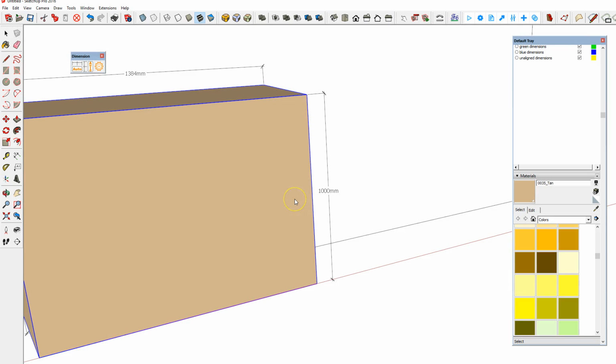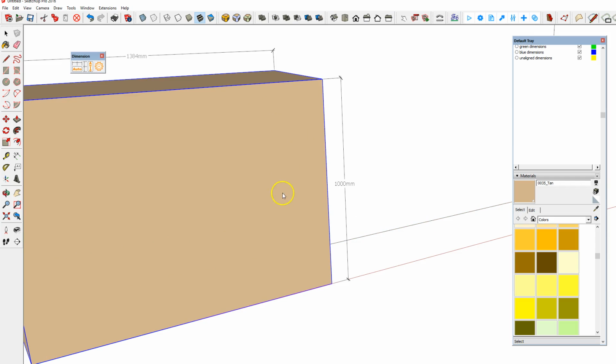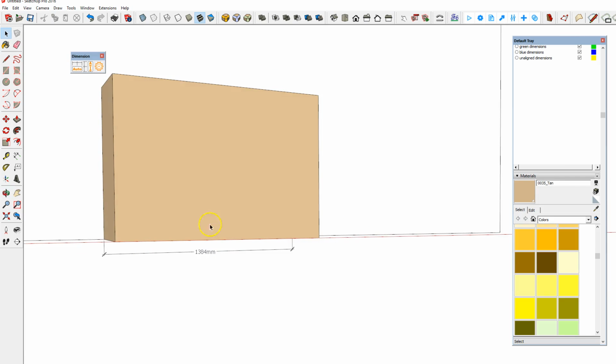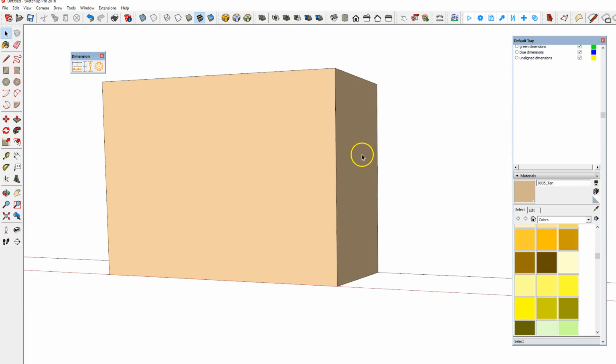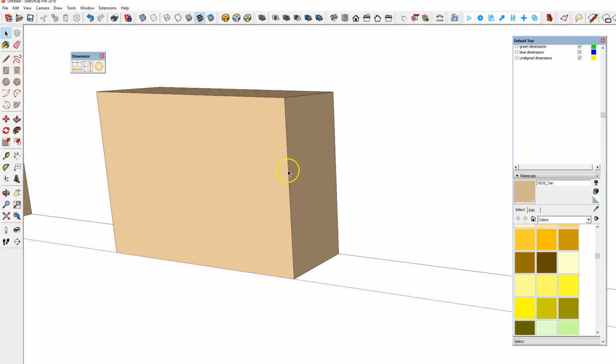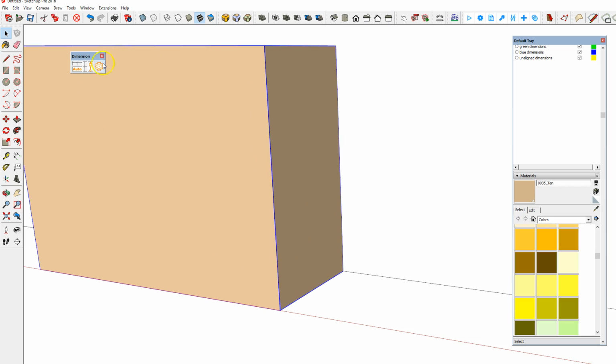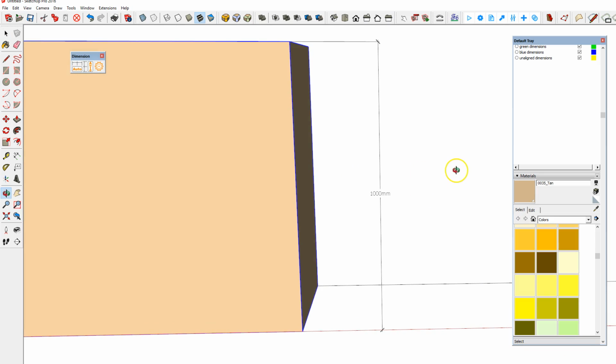Again, you can type in your offset distance, say 300, press enter. I did another operation in between there, so that didn't work. Let's just do that again. So I'll point this to my nearest edge, this edge. Click the vertical button. See the distance it's set off here.